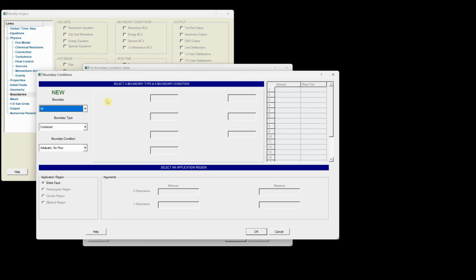However, we did hollow the stack out, so there is a hole in the bottom, and whatever mass flux we apply there will go through the hole. So let's pick mass flux and temperature. It's going to be a value of 1.99 kilograms per meter squared per second, and the temperature will be 350 Kelvin. And it's going to be hydrogen, but we don't specify that here.